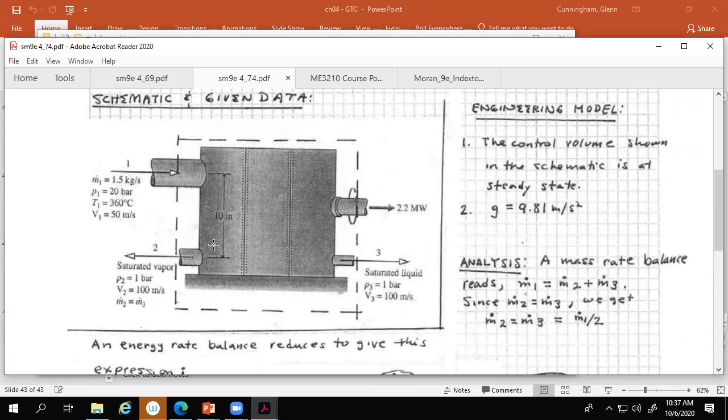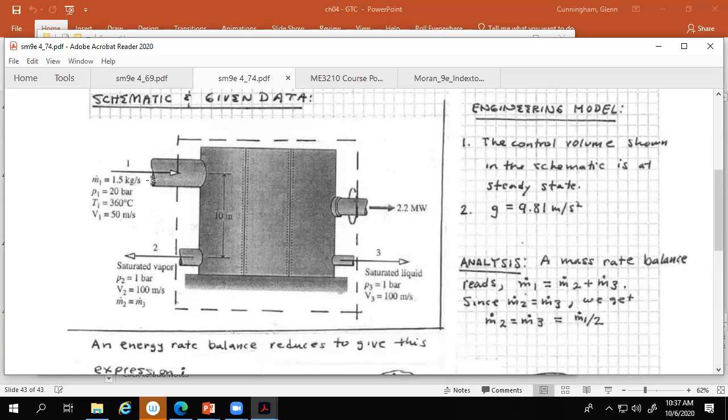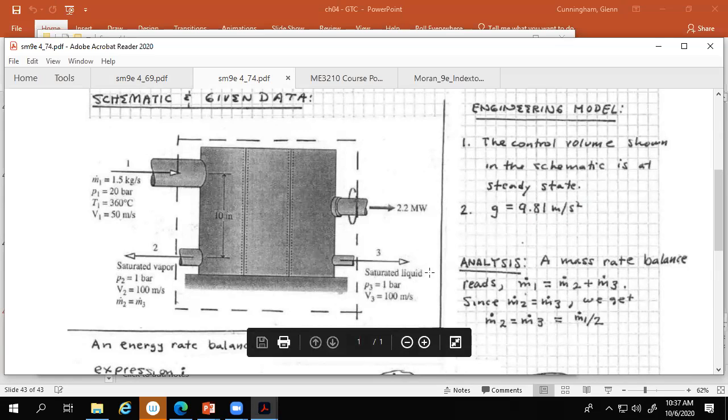And we're going to break it into several useful different energy streams. We're going to get some electricity out of this. So maybe this stuff comes in, maybe this is steam, whatever it is. And it goes through a turbine, turns a generator, and electricity comes out. And then we got some hot water that comes out, we got some saturated vapor that comes out, and we use these things in a manufacturing process.